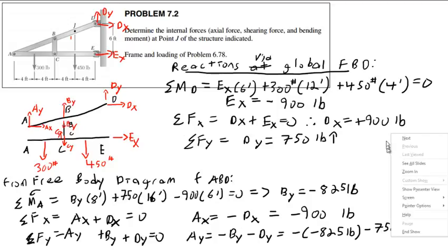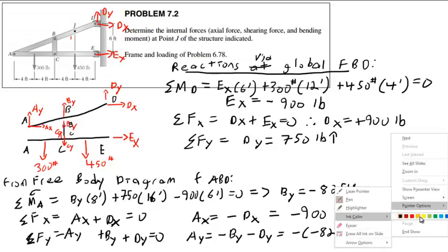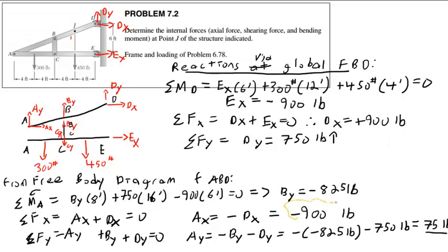So I'm going to need this one. Let me just go ahead and put little circles around the things I'm going to need. I'm going to need this thing here, this one, this one, and this one. Questions on any of this so far? This isn't the final answer. Again, what I'm doing here is finding all of the external forces on member ABD, and from that I'm then going to find the internal forces in member ABD. Okay? All right.